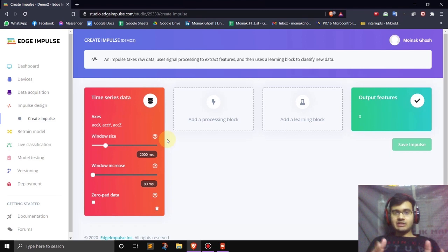What you've actually done is that you have taken a large number of samples from your accelerometer, sampled at a certain frequency. For my case, it was 62.5 hertz. So at 62.5 hertz, you've taken thousands of samples in the duration of 10 seconds. So you've taken around, say, 625 samples. What this window size does is that it takes a window and keeps breaking the entire data set into parts.